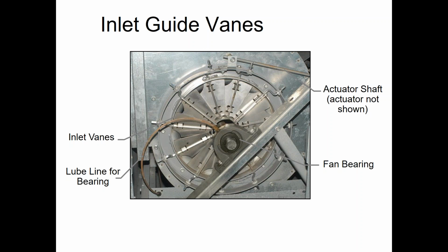If I've got a zone that normally can move 1,000 CFM and it throttles back to 350 CFM, that means I've got to cut back the air handler 650 CFM. The way we're going to do that is by measuring that static pressure in the duct, and as the dampers modulate back, the static pressure will build, and then we will do something at the air handling system to reduce that static pressure. There's several ways we can do that.